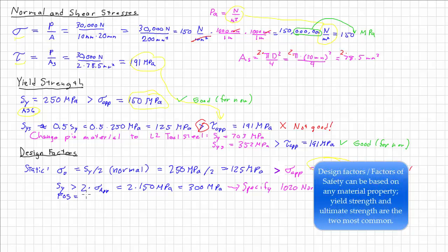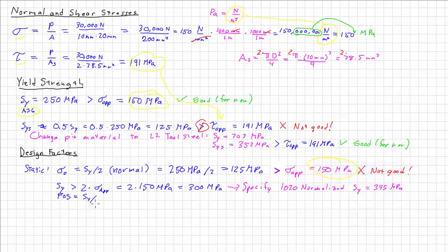It is going to be the yield strength divided by the applied stress, 345 megapascals divided by the applied stress, which was 150 megapascals.